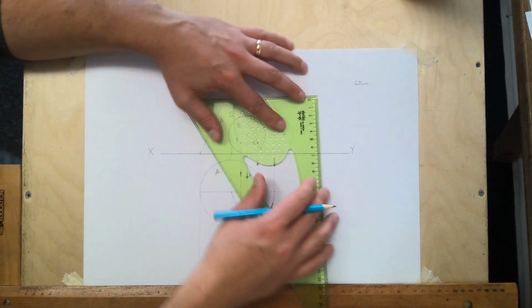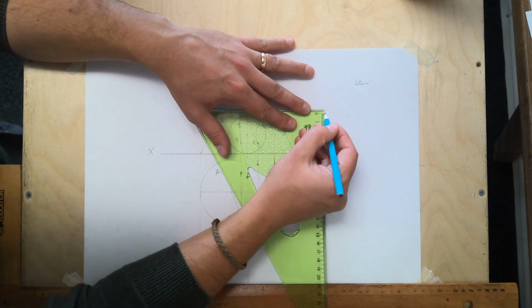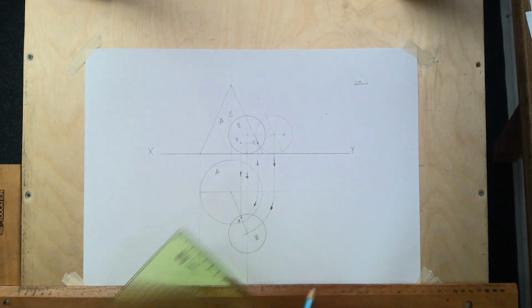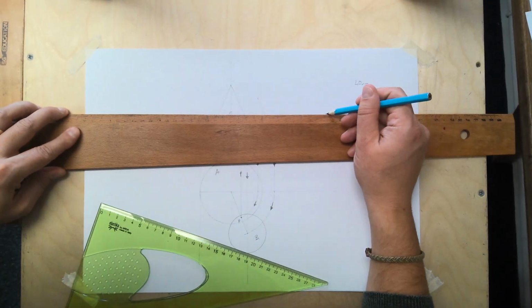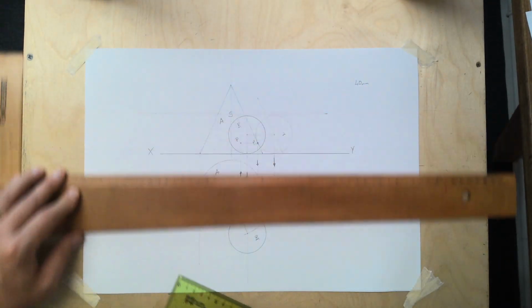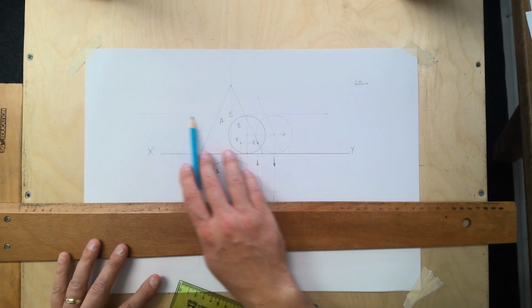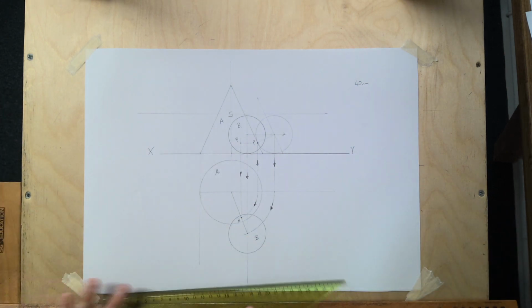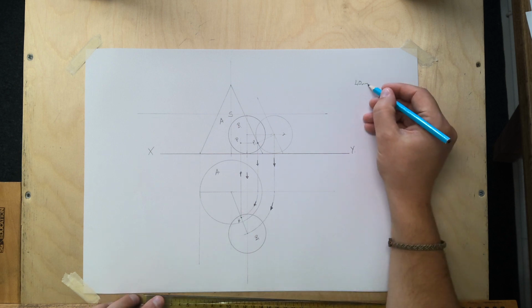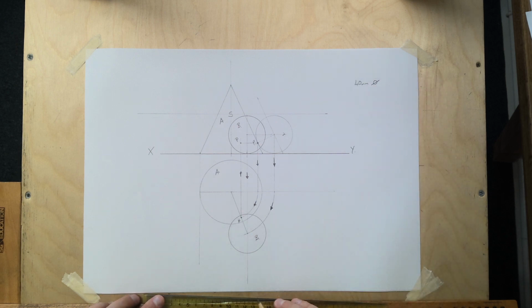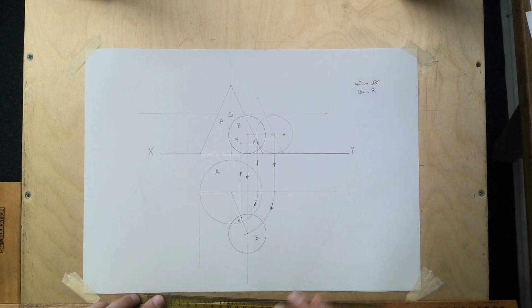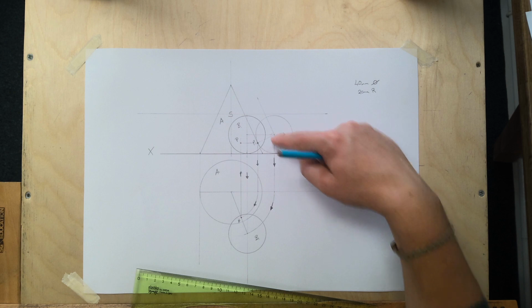So first things first, the 50 millimeter center point is going to be off the ground. I'm going to pop 50 millimeters off the ground over to one side, get a light line, and send it across. So we know somewhere along here we're going to have our sphere because it's 50 millimeters off the ground. Now we're told it's 40 millimeters diameter, so therefore it is a 20 millimeter radius. So what you're going to do is just like we would have done here.